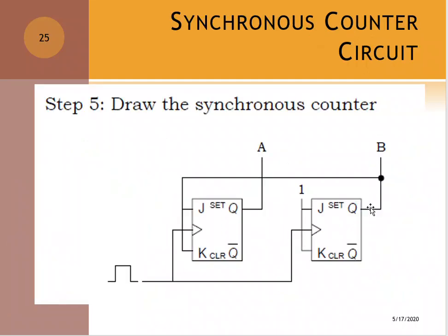And then this is the flip-flop for B, so you drag 1 wire from the Q of the second flip-flop, connect it to B. And then this one is the flip-flop for A, so this is the input, so drag 1 wire from Q, connect to A.